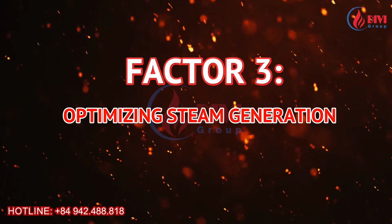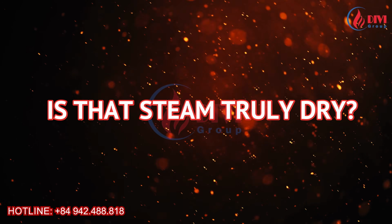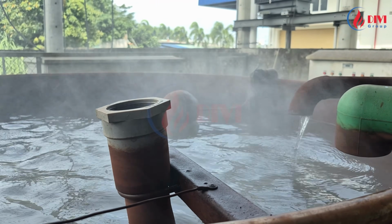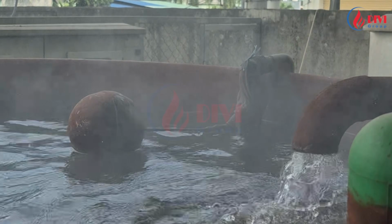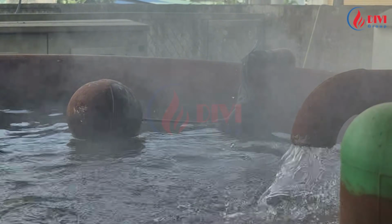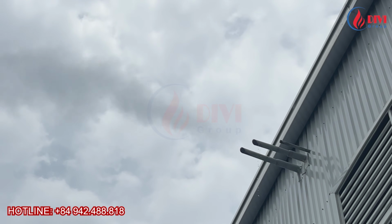Factor 3, optimizing steam generation. At this point, many people may think that once enough heat is supplied, water will simply turn into steam. That is true, but the real question is, is that steam truly dry? Imagine that steam still contains tiny water droplets carried along with it. This means the water has not been fully converted into dry steam. This significantly affects boiler performance because these water droplets transfer heat poorly and can actually absorb useful thermal energy from the steam. As a result, the energy content of the steam is reduced.